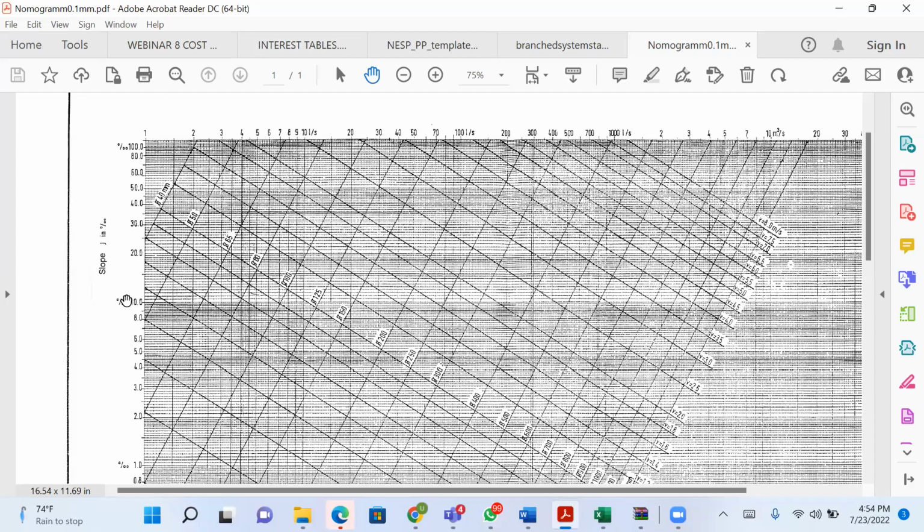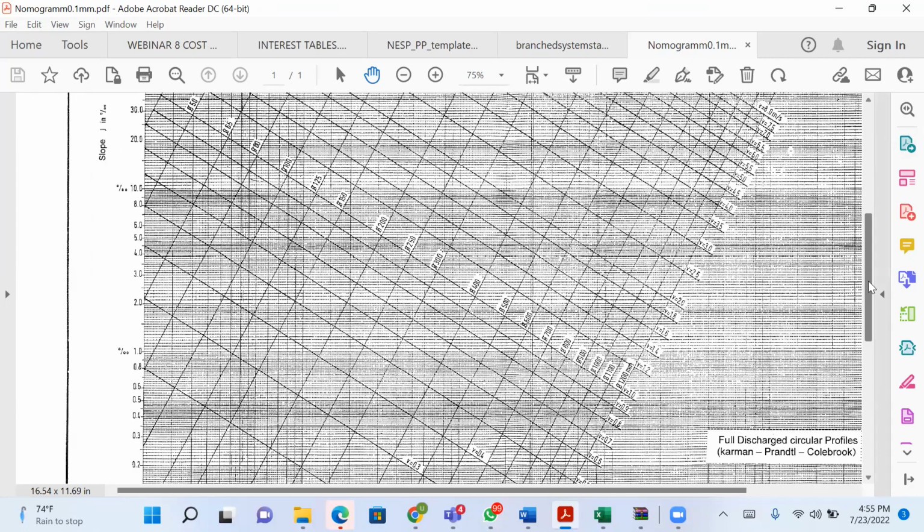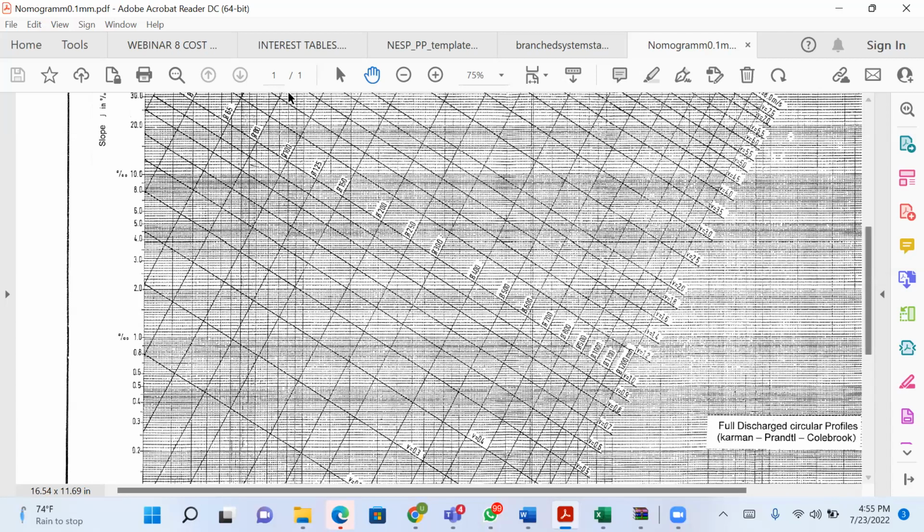Any question? Also, the vertical is the slope. So when you have a discharge and you have your slope, you now read off the pipe size. So this diagonal line represents the size of pipes: 100 mm, 125, 150 mm, 200, 250. If you get to any point of pipe, if you come in between two pipes, you choose the biggest of them.